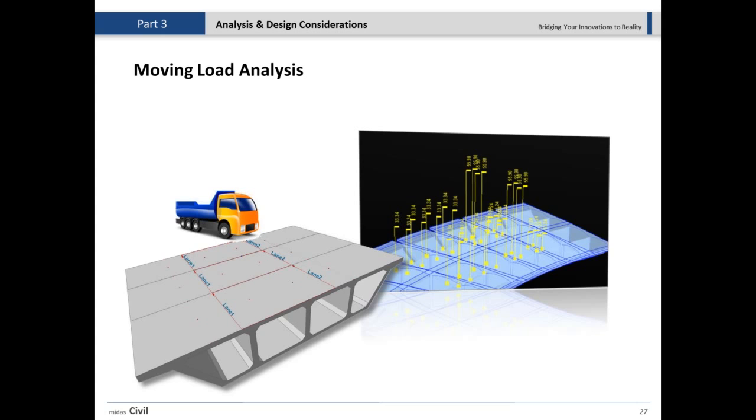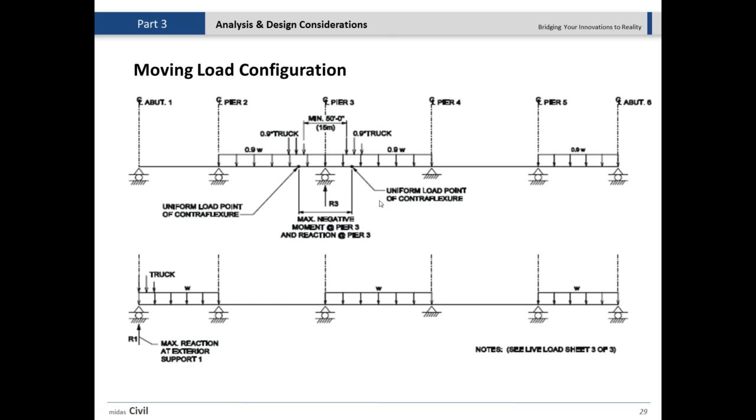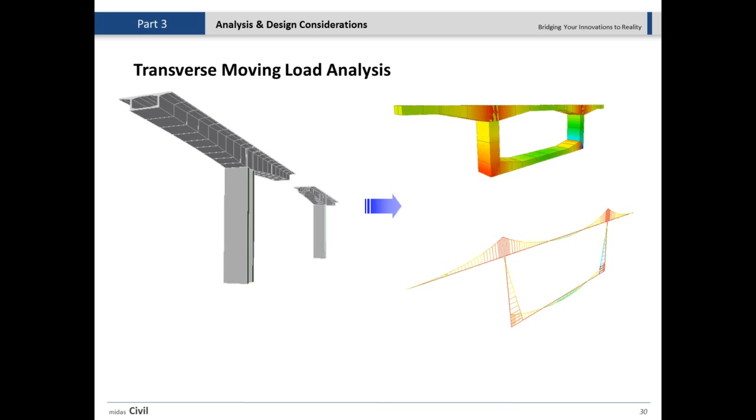So although you model them with the spline model, you can define different lanes with different eccentricity, and define the load arrangement on the structure, and the software automatically applies different possibilities of the loading on the different lanes, and provides you the extreme results for both negative bending moments and maximum bending moments, and all the deformations. All of them will be provided to you automatically.